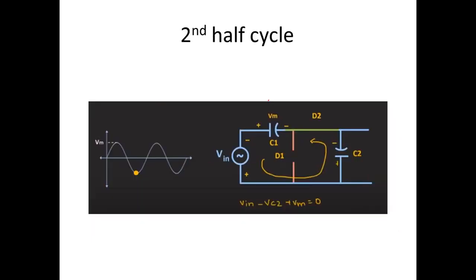So this is again a voltage doubler circuit, because it doubles the voltage, but now we are getting the output across the capacitor C2. This charge and this charge, both of these two will add up, and the current from these two will combinedly flow through this capacitor C2. So the charge now will appear as Vm, both of these two.